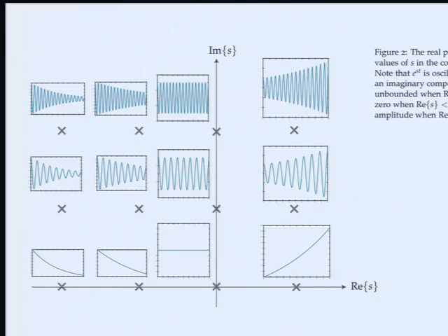Poles that are really far in the left half plane die down very quickly, even if they oscillate. Poles that are on the imaginary axis don't die away. They just continue oscillating, or stay constant if you're exactly at s equal to 0, right? Poles that are close to the imaginary axis, although they're in the left half plane, will keep ringing; they will perhaps die out, but it will take a long time, all right?